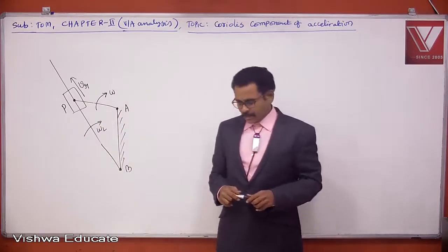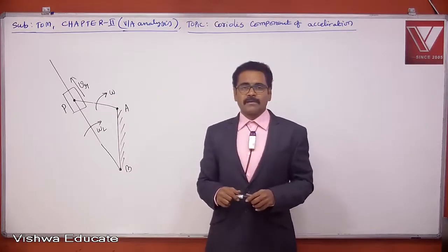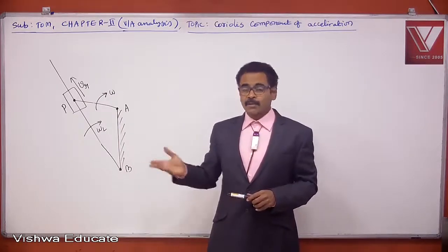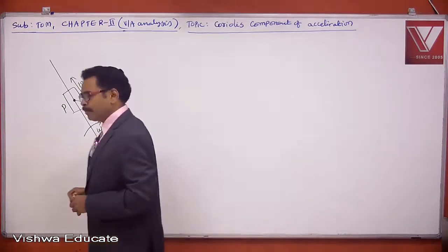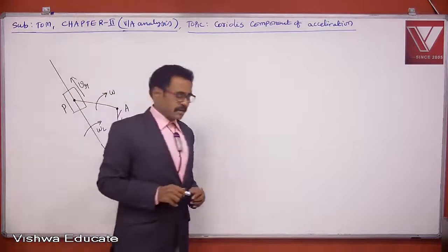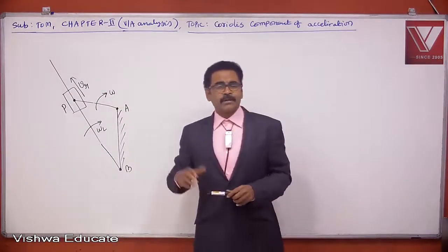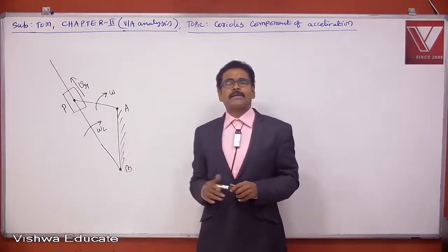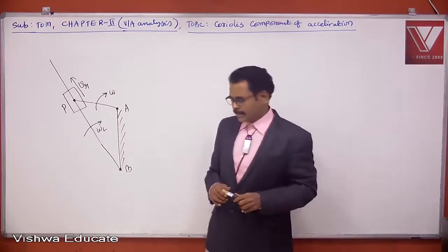Is Coriolis component of acceleration present in single slider crank mechanism? Definitely no. In single slider crank mechanism, no point of the mechanism carries both radial and rotary motion. Write down the next point.